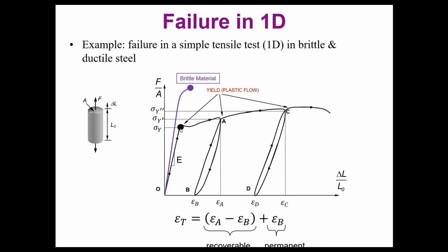And there is another reason why we define the failure when the yield plastification starts: in there we need to define something mathematically to be able to capture this change in the behavior from elasticity to plasticity.